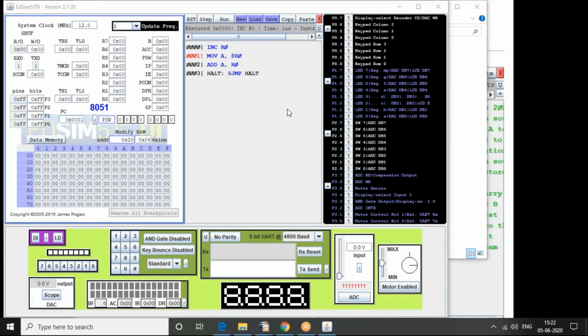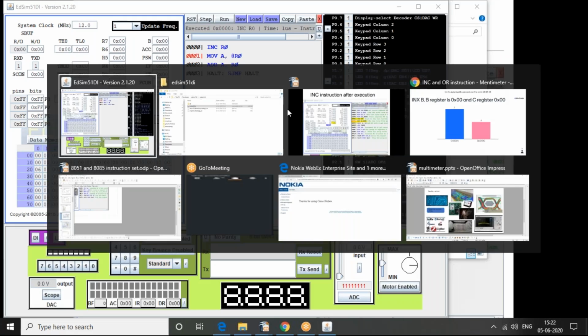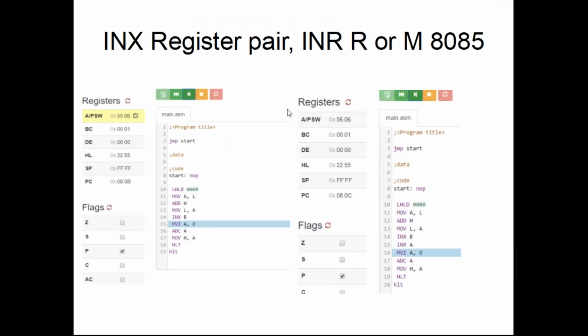So this is some property which you should remember because this might come as a problem most of the times. You would expect that the carry flag will be set, but it won't be set because that's not very trivial for us. Okay, I'll go to the next. We looked at INC and all those stuffs. Similarly, you have an instruction called decrement, which will decrement by 1 instead of incrementing by 1. But then all other rules apply. The carry flag won't be set.